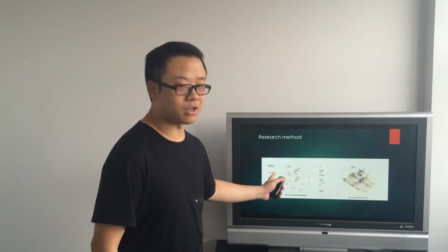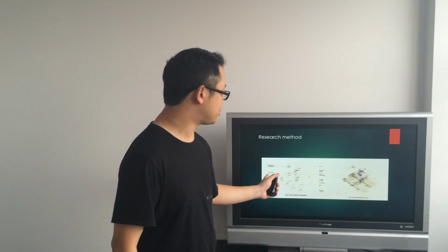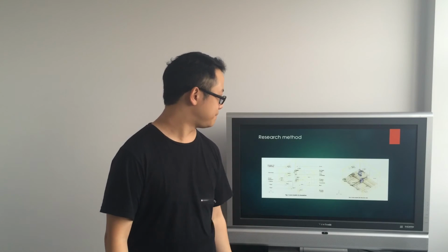This is the model of my simulation. In this room model, two openings, the door and the window, can be considered as sources of the system. The television, human body, and other layouts will exchange heat with the flowing air. The grids close to the objects are non-uniform to capture the shape of the indoor layout.